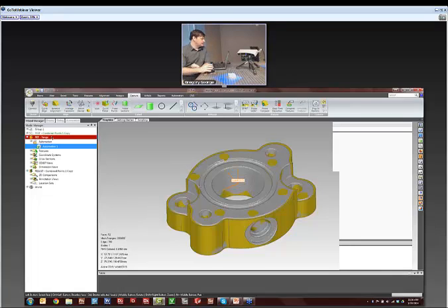So we can actually create the inspection routine ahead of time. It is important to point out that you would need the CAD model, and then from there you can set up a basic routine. Often what I will do is take the CAD model itself and convert it over to a sample scan data set, just a fake piece of data, to then create the whole routine accurately. Then I can throw away that sample scan data set and bring in the real data once I have the throughput.